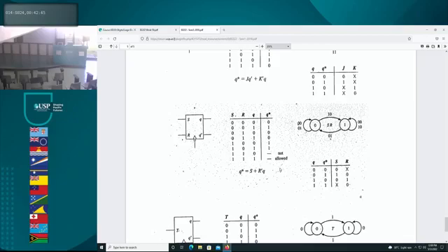I showed you piece by piece how we went from the latch to the flip-flop, from the flip-flop to the truth table, from the truth table to the characteristic table. This is the characteristic table. What does it have? You have the 2 inputs and your current state, and you predict what will be the next state. Remember I gave you an example of a video game of sorts, right? So that's the characteristic table.